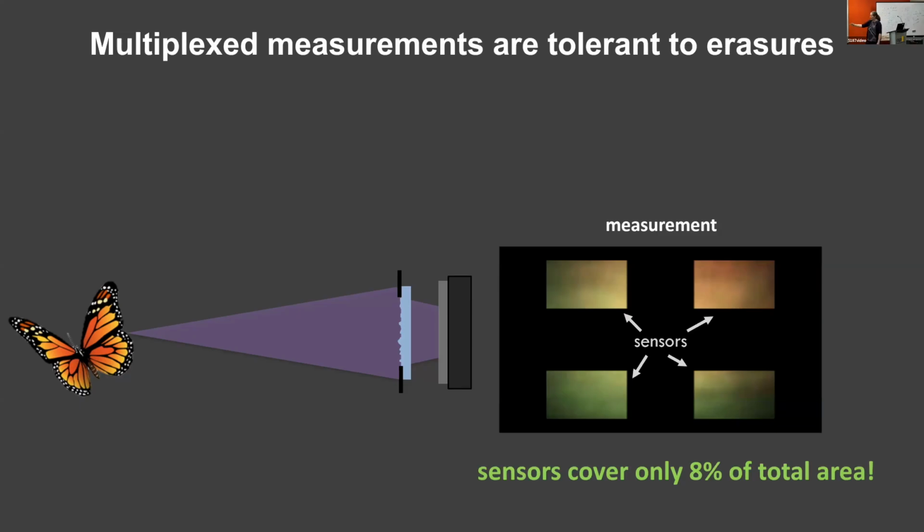what if I'm trying to do an array of sensors? There are reasons why we don't have a 500 megapixel sensor available. There are circuitry reasons for that. So you can get a bunch of sensors, say a 2x2 array, each one a couple megapixels, but you can't put them directly next to each other. They always have some border around them for circuitry, which is important. And so you always have these gaps between them. This is why you wouldn't make a sensor array for a regular camera.